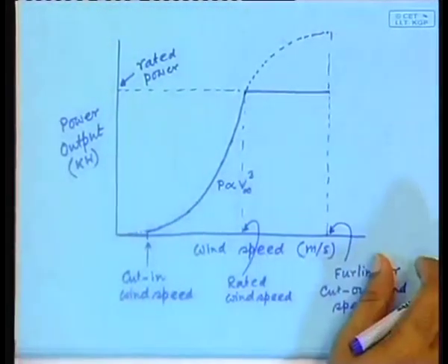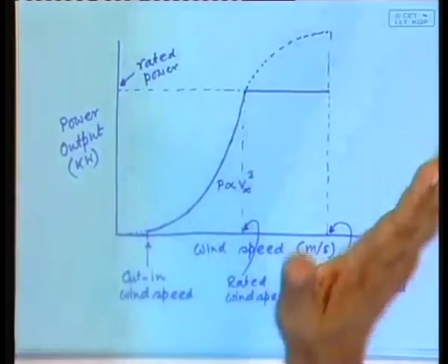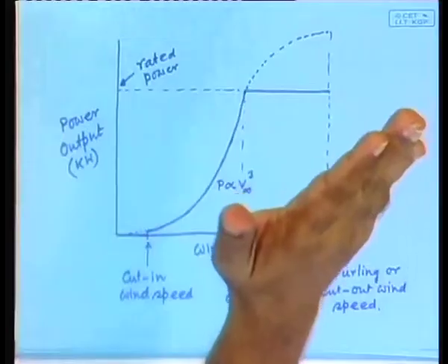One is where, as you have seen, so far we were controlling the pitch angle in order to obtain the maximum power output. Suppose we now deliberately do it wrongly, what will happen? It will give less power output. So one way is to pitch it in the wrong direction, so that the power output reduces. That is one means available in your hand. That means the mechanical power output will be kept constant by changing the pitch angle in such a way that it gives out less amount of power.